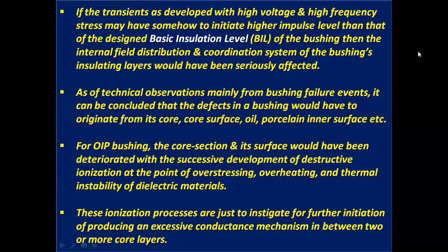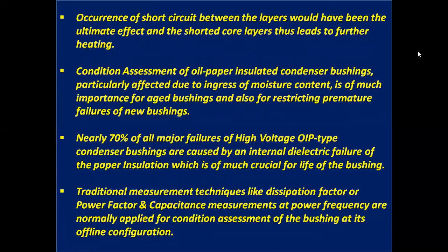These ionization processes instigate an excessive conductance mechanism between two or more core layers. Short circuit between the layers would be the ultimate effect, and the shorted core layers lead to further heating.